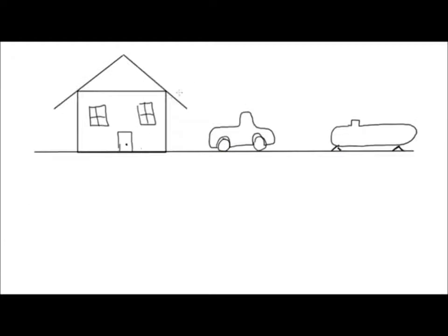Alright, I'm just going to talk a little bit about the difference between absolute pressure, gauge pressure, and vacuum pressure. So imagine we have all these things here at sea level. We have a house, we have your car, and we have this tank full of something, some gas or something. Alright, so first of all we say that we have a P atmosphere. And in thermodynamics and fluids, usually at sea level, we say that the atmospheric pressure is around 101 kilopascals. Now this is actually an absolute pressure. So we're going to say that this is ABS, just subscript ABS, and that just means that it's 101 kilopascals more pressure than a perfect vacuum, or more pressure than just a space full of nothing.